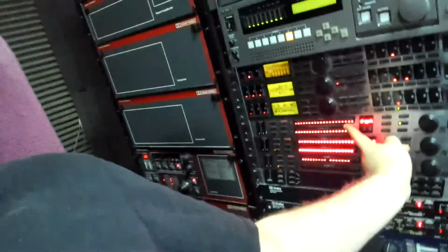bandwidth, and the problem with when you widen the Q bandwidth, you go below and above neighboring frequencies. You got to observe your frequency resolution. It's hit and miss, trial and error. But there's just simply not enough Q bandwidth. Or not Q. There's not enough parametric EQ filter bands. This only goes up to 20 per channel.